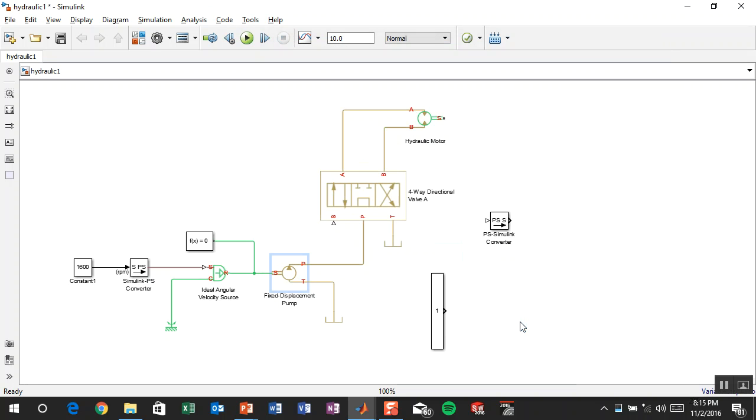Volumetric efficiency means stuff kind of stretches when you apply massive pressure? No, it means, think of it like a cylinder, like if you have a cylinder that you're using like a pump, right? And maybe you're pushing through something that requires 1,000 pounds of pressure, right? And so you're getting some flow out, and you're pushing this other cylinder, but some of that oil leaks around the piston. So this is saying 10% of it will leak around the piston, which is actually not bad for piston pumps. But things like gear pumps are like 75%.